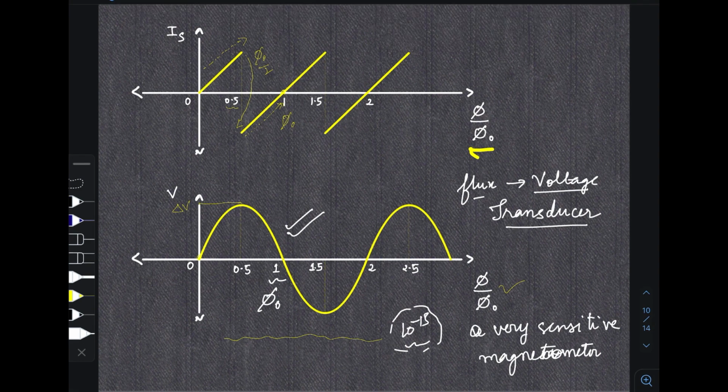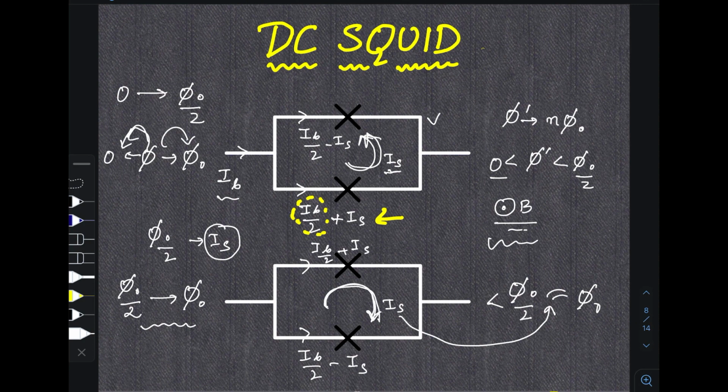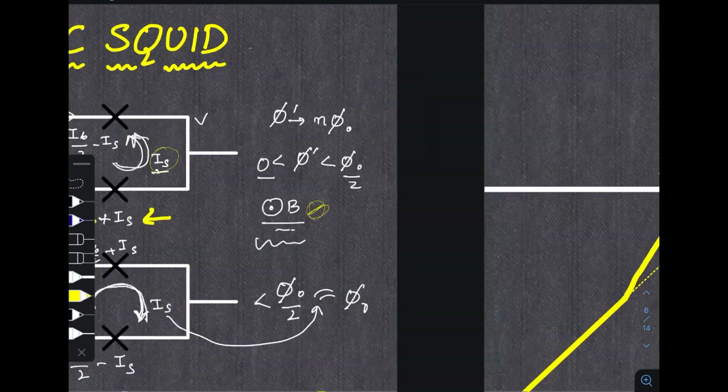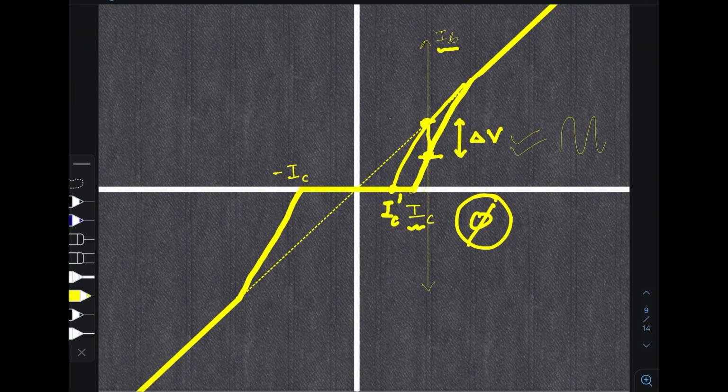So summing up everything, what happens is as we change the magnetic field, an EMF is developed, the screening current is developed, and because of the screening current, the critical current which we can send into the Josephson loop decreases. That is, for n phi naught, the IC will be the maximum IC, which is the normal Josephson junction. As we increase the phi naught, we can see that the IC will be decreasing, and at n plus half of phi naught, we will have the minimum IC, that is IC minimum.